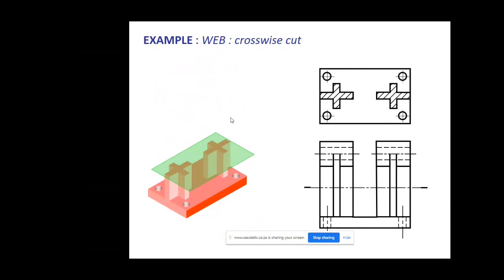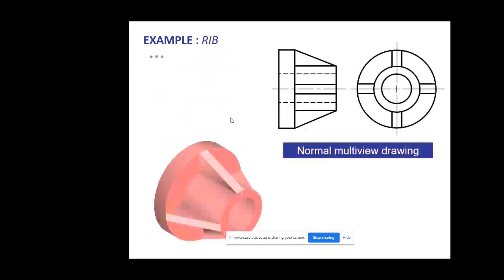So the next slide is another example where they show a rib. And you see, this is another example of a rib to a learner who's never seen it. And then it's also in third angle. And for you to show a full sectional right view of a rib, it needs to be cut. So you need to have a blade that demonstrates and shows the learner how it is cut.